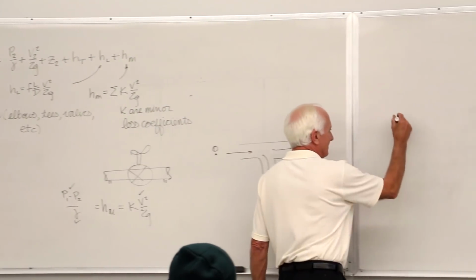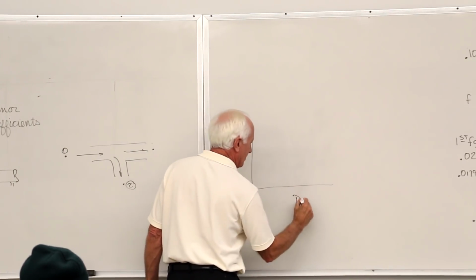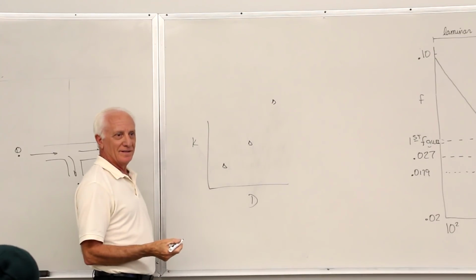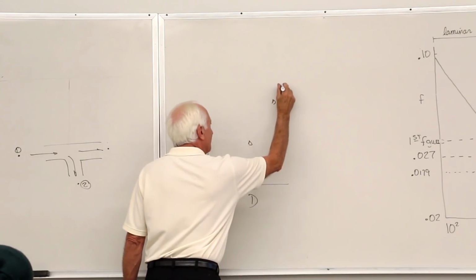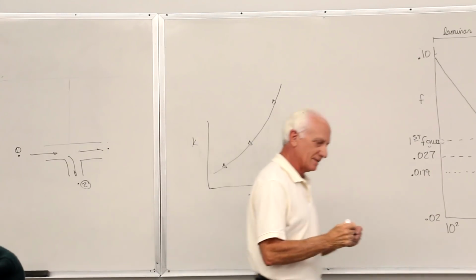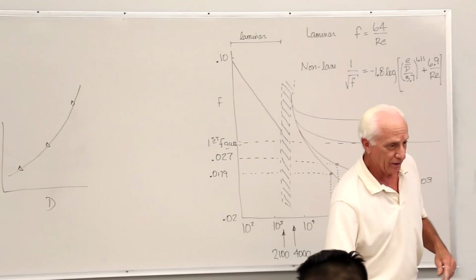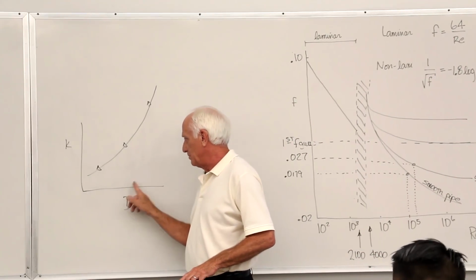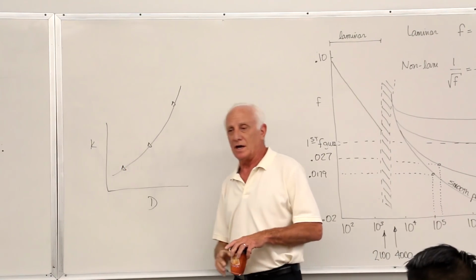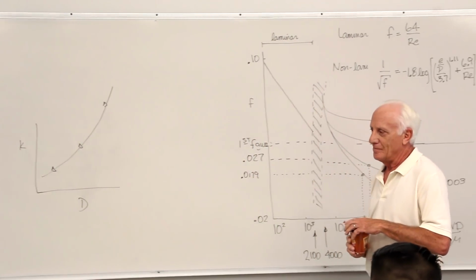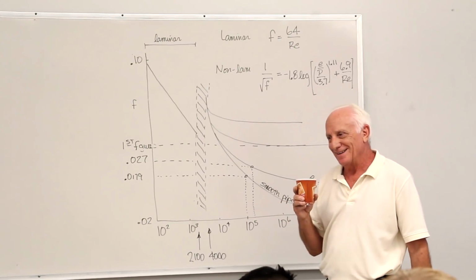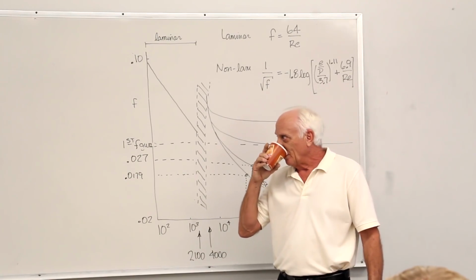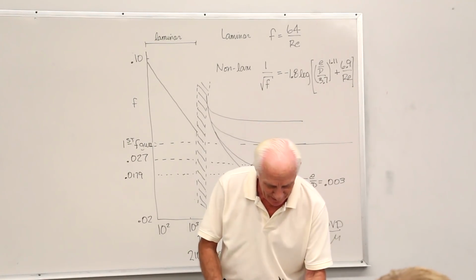What you do is you plot K versus diameter. There's 3 values given there. Here, here, and there. Take your best guess on Excel. Draw a line through it. There you go. Now find 7.5. Don't interpolate linearly unless you know it's linear. No. Plot the values and then go to the diameter you have and read across, because you'll find out they're not linear. Okay, so that's how you find the K values for different diameters than on that sheet of paper. So that's what we do with that.